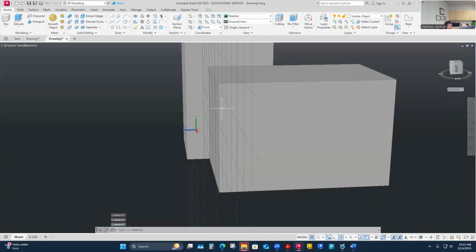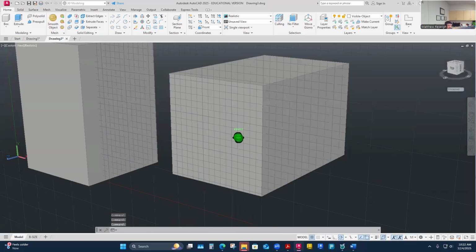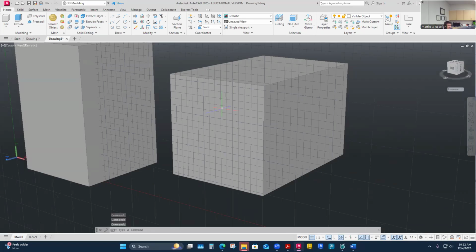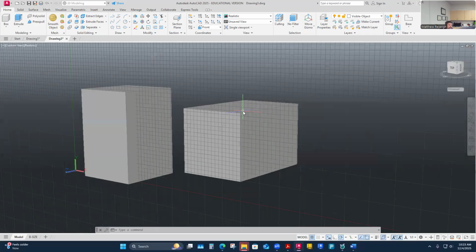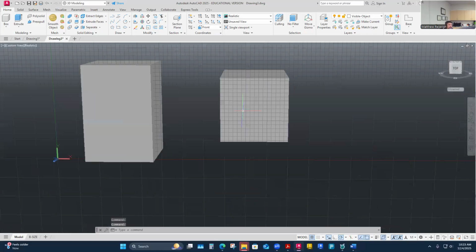This is confusing. I don't want to go too deep into here to confuse you, but if I want to draw a shape in a specific direction from a grid, I've got to be on that grid like I would on an isometric pictorial in some ways. It's just that I have a lot more grids to choose from here. Sometimes when I'm drawing, I might just pick which grid it's going to be on. What's going to matter, I should say, is when you go to a drawing, it's going to consider this the front view. So calling this the front is really for me thinking of how I want it to show on my drawing as a front view.